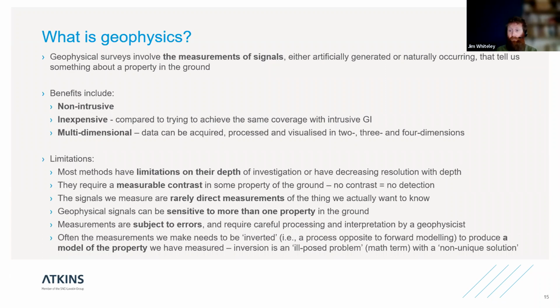And the main benefits, as I've touched on already, is that geophysics is non-intrusive, so we don't have to break ground to get much of this data. At worst, we're having to put in some electrodes, maybe to 20, 25 centimeters depth, or some geophones, which have got spikes maybe of 10 centimeters. It's inexpensive, and when I say inexpensive, that's really in relation to understanding the site spatially. So the amount of money that you have to spend to get the same volume that you would with an intrusive investigation is far, far less. So there's a cost saving there.